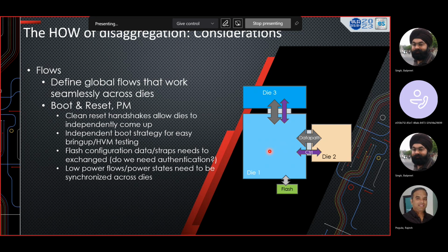When we talk about DMAing things, we are probably talking about the data part, where it's a runtime thing. You have huge amounts of data coming in from your PCI I/O, and you want to shift it to the memory or some other accelerator. That's where you want to talk about DMAs and optimizations.